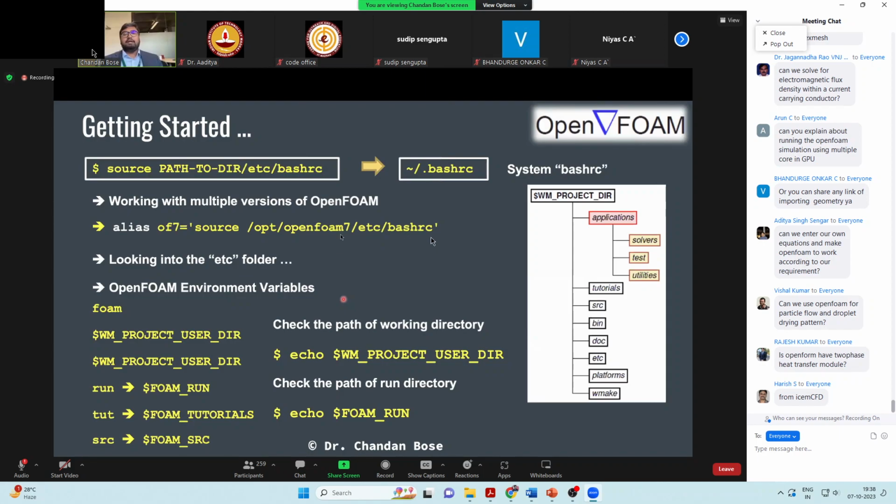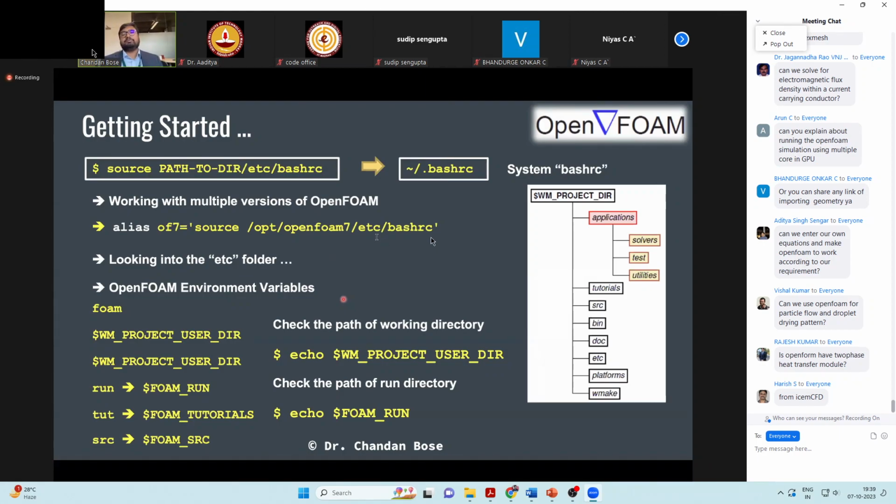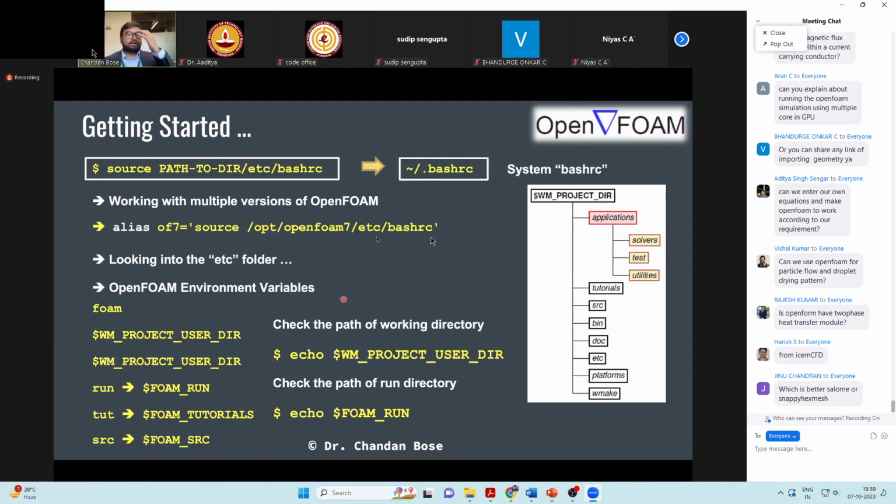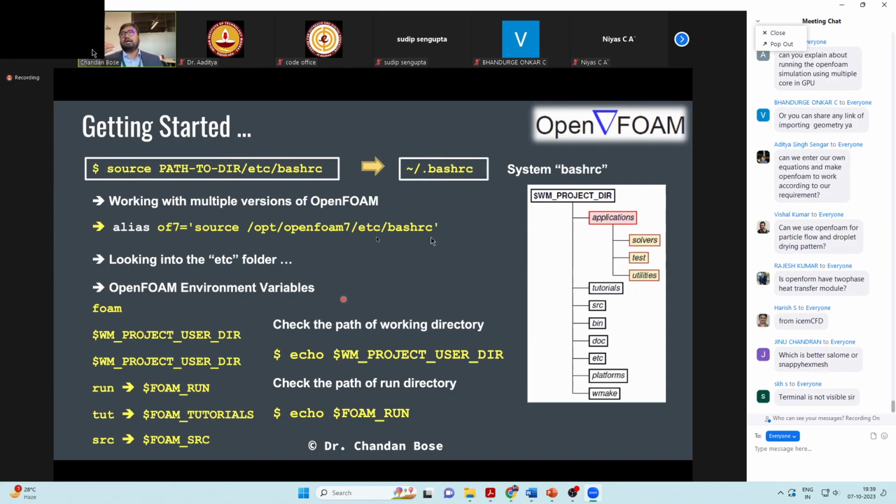Right. Again, for ICEM CFD, it's a bit of syntax, right? So I don't remember all of the syntax for all of the different meshes to import, but it is available online. I can share the link again with the material for different kinds of third-party meshing software. What are the commands to convert them to a polyMesh directory? But it's pretty straightforward. It's just one line of keyword to convert it to a polyMesh directory.